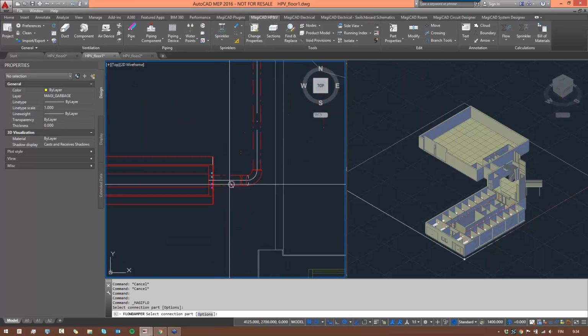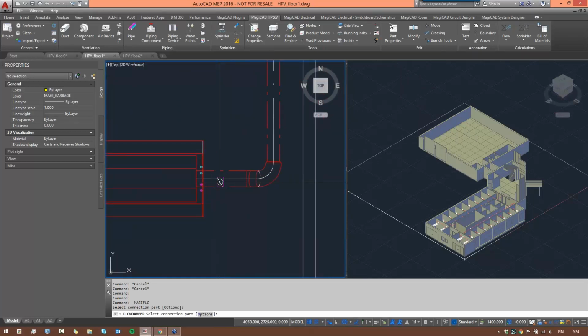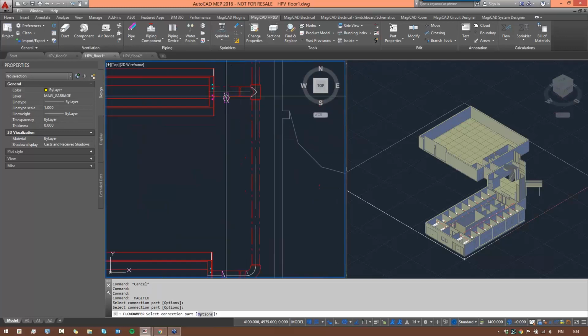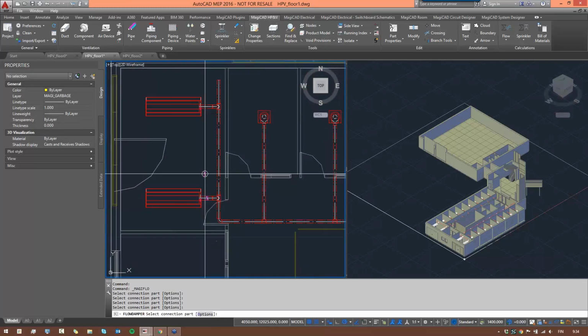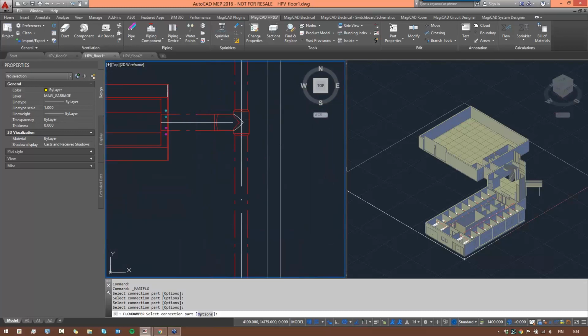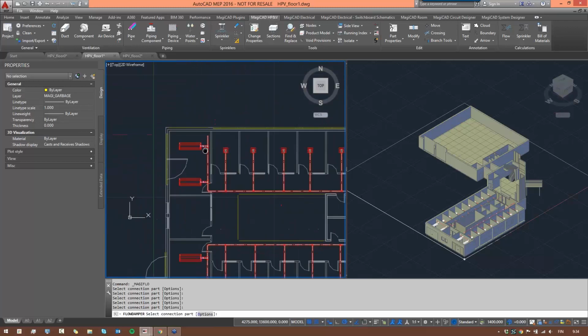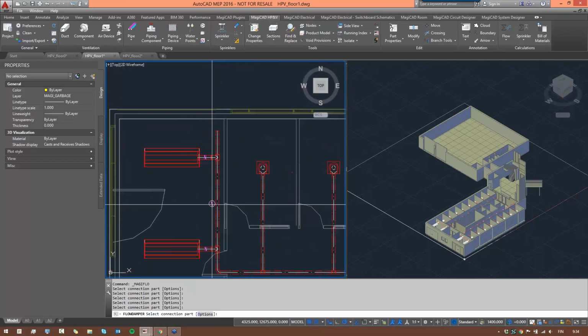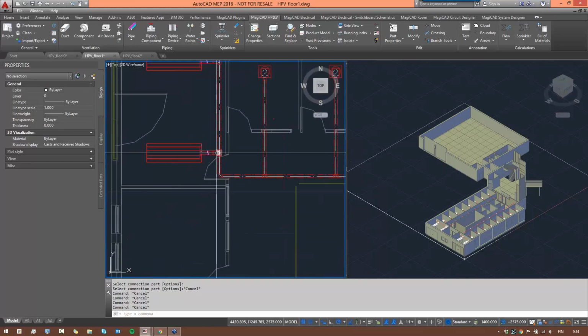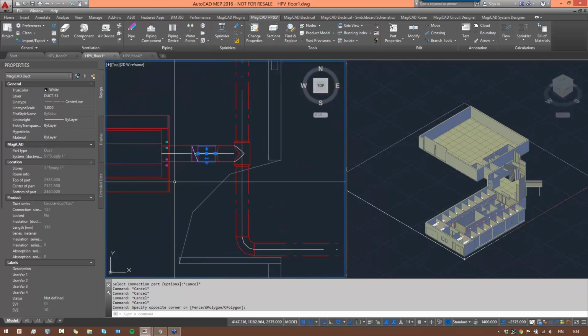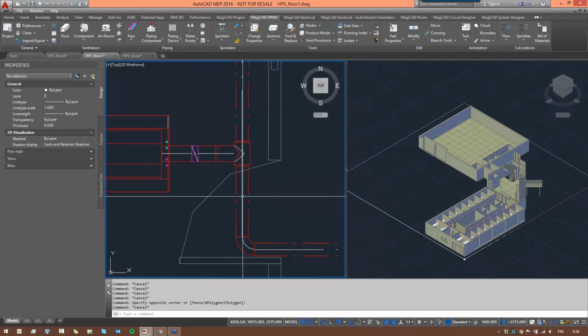Oh, there it is. Again, it mysteriously froze for a second. So flow damper, select connection part. I'll have to show where it's actually installed onto that duct, as well, and these two here. So it's automatically sized to that branch size, using the 125 here, which is our connection size for the duct.